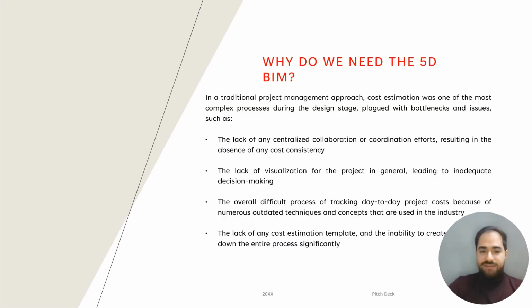So why do we need the 5D BIM? In the traditional project management approach, the cost estimation is one of the most complex processes during the design stage, mainly in the concept design, because in the concept design, the designer gives us a generic model. He mentions that we have a door here, but we don't know the specs of the door. We don't know if it will have fireproofing or not, a fire protection or not. So all of these trades or assets are recognized by the cost manager, but the experienced one. So it is one of the most complex processes to do, even in the later stages.